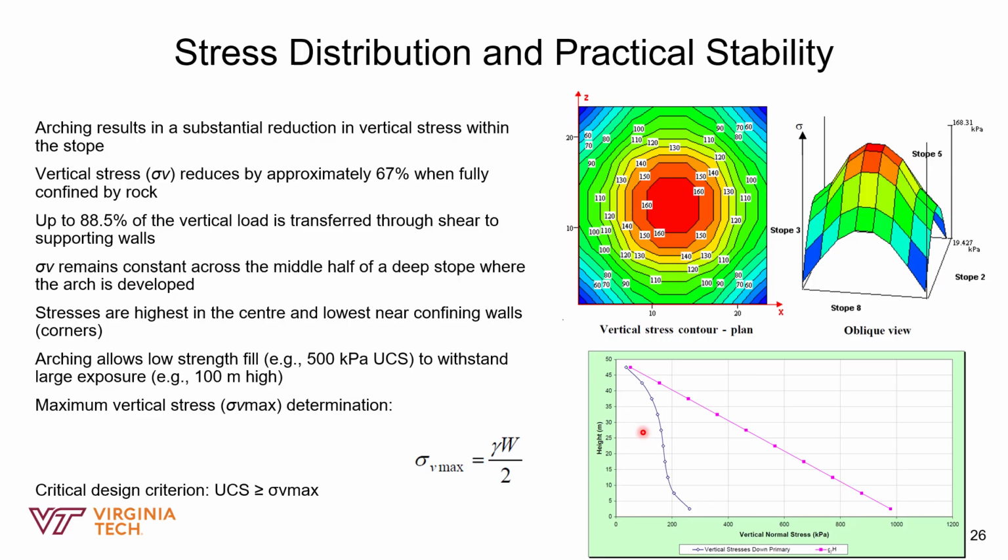Looking at the trends, the stress for the arching material is substantially lower than the hydrostatic stress profile. The stress increases briefly near the top and bottom of the arching profile, but in the middle part the trend is fairly constant. This constant stress proves that the entire weight of the overlying fill in the central column is successfully transferred to the walls by shear.